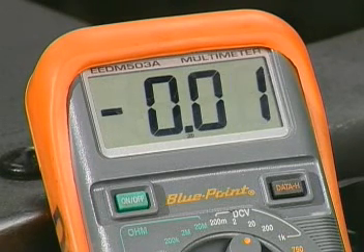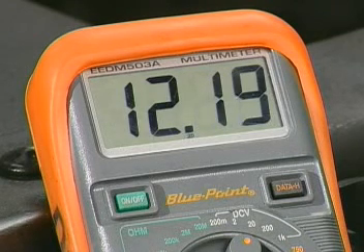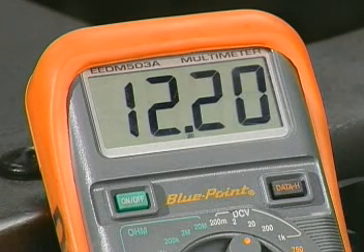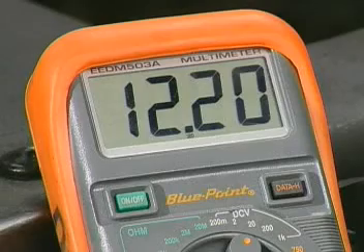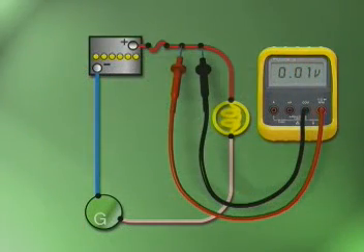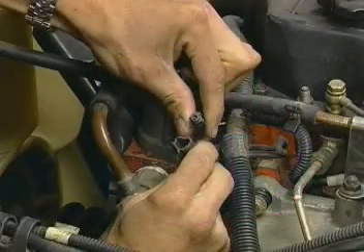The total of all voltage drops across each section of the circuit will equal the voltage supplied to the circuit. The total voltage drop for a complete circuit should not exceed 1 volt direct current. Voltage drops greater than 1 volt should be checked for high resistance or loose connectors.